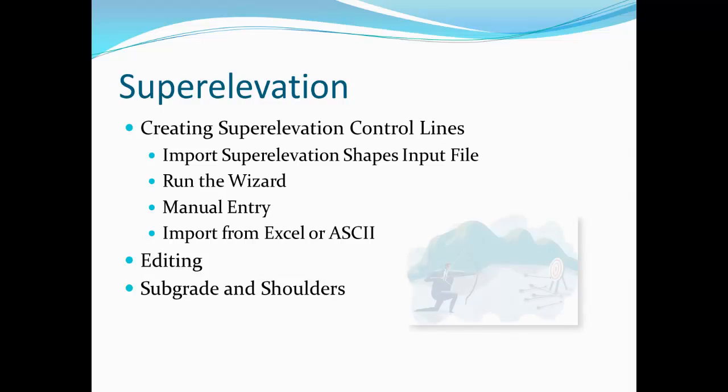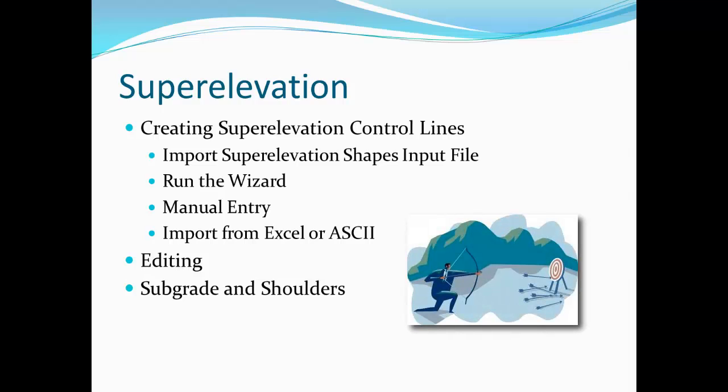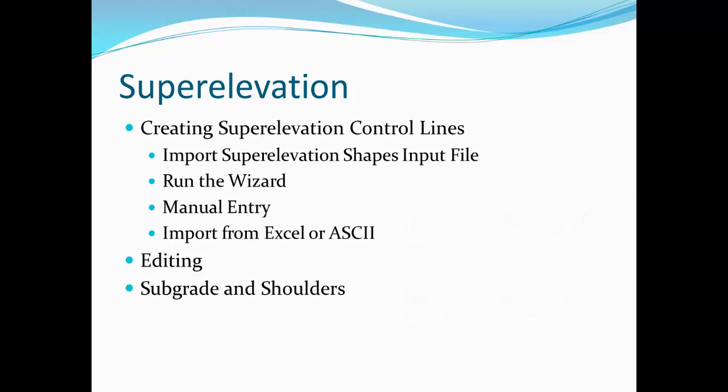Personally, I have not had much luck getting the output from either the old superelevation shapes and input files nor the superelevation wizard providing me with the output that matched my hand calculations without requiring any editing. I can tell you that we are working on trying to resolve that issue in the SS3 release, and that the process for entering superelevation data in SS3 is a hybrid of both the old shape method and the new wizard method.